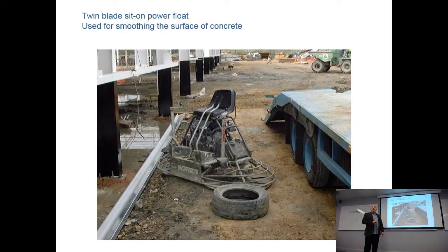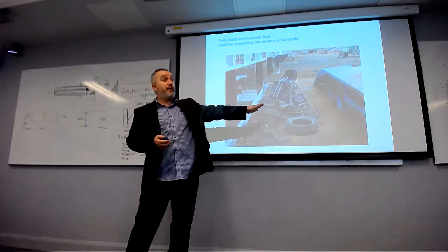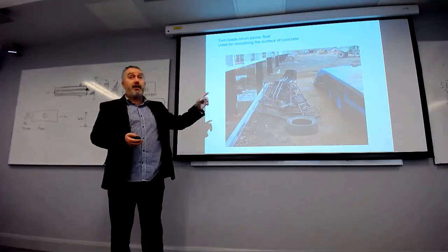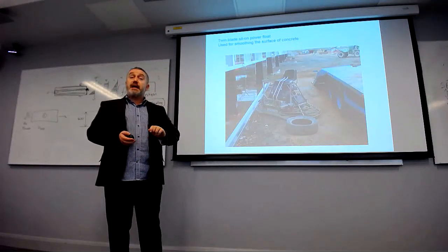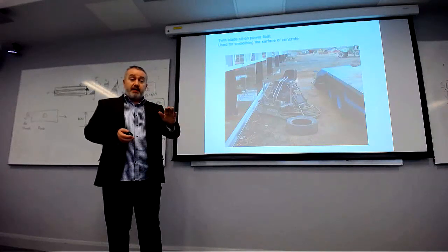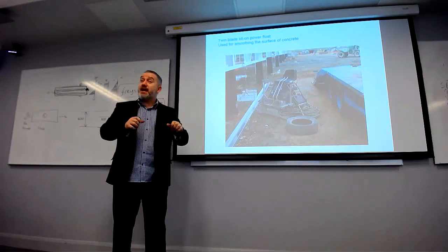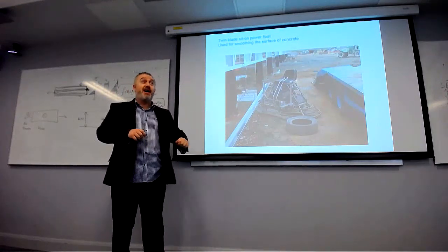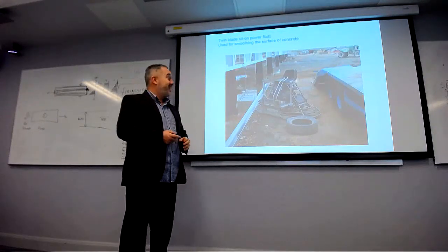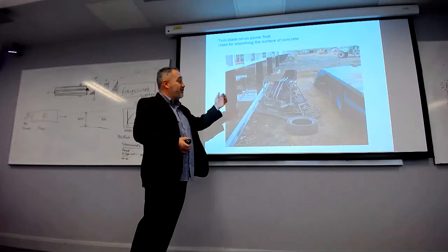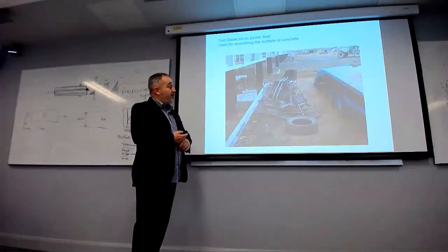No. We went on a site visit to a school, and they had put concrete across the whole of the floor. And then they went across with a power float, which made it nice and smooth. But then they found out afterwards that the type of tile that they were putting down needed a rough surface to stick the tiles to. So they then had to go around the concrete with a grinder and scratch all of the surface. Most of the time you have a smooth surface. It's just with that type of finish that you're putting on, you needed a rough surface.